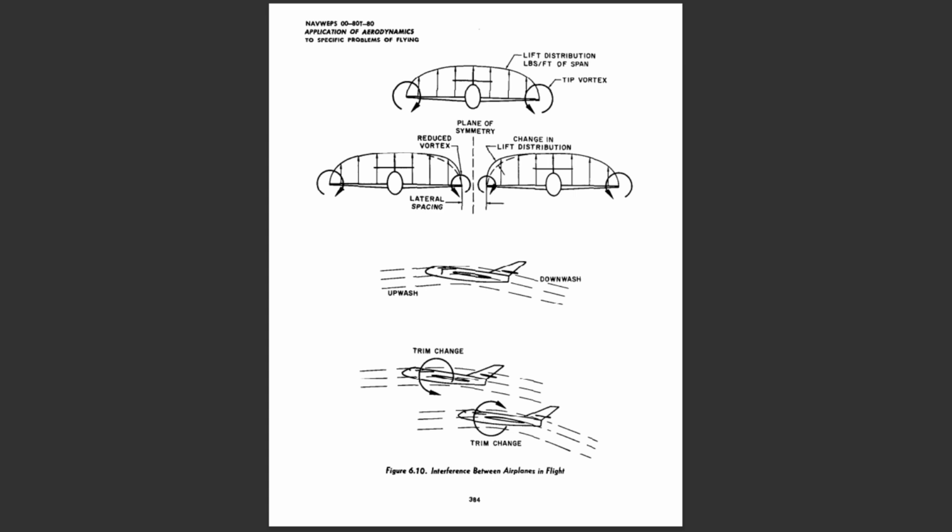In a close diamond formation, the leader will be able to feel the presence of the slotman even though the airplane is not within view. Obviously, the slotman will have a difficult job during formation maneuvers because of the unstable trim changes and greater power changes required to hold position. A common collision problem is the case of an airplane with malfunctioning landing gear. If another airplane is called to inspect the malfunctioning landing gear, great care must be taken to maintain adequate separation and preserve orientation. Many instances such as this have resulted in a collision, when the pilot of the trailing airplane became disoriented and did not maintain adequate separation.